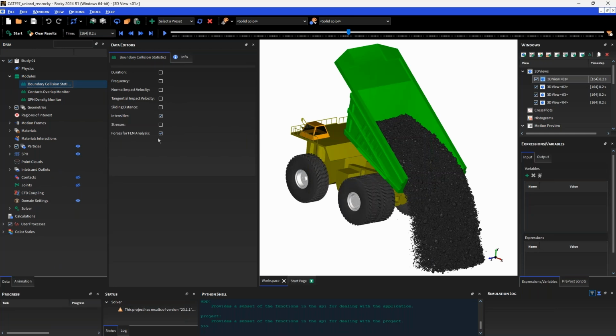Now, as a result, also, the resolution and the quality of that surface mesh becomes important. So element size or triangle size will correspond to how much information will be smoothed or averaged out. And you'll want to avoid highly skewed meshes, as that will, of course, directly skew results or the load mapping onto the geometry. So the recommended triangle size in these cases, as a general guideline, is to have them no smaller than the smallest particle size in the model.